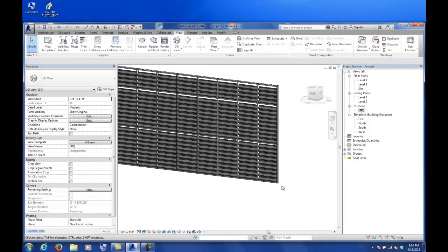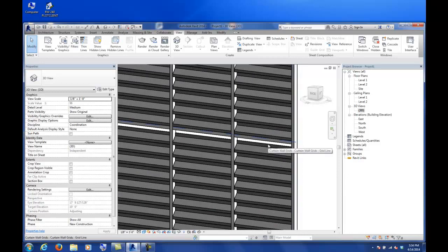So now you can draw it however you need to, and the comment was about the height was 75 feet. Obviously, if you're going to have a louver that's 75 feet, you're going to have these mullions at probably 5 feet intervals or something like that. That's going to break it apart into individual components.